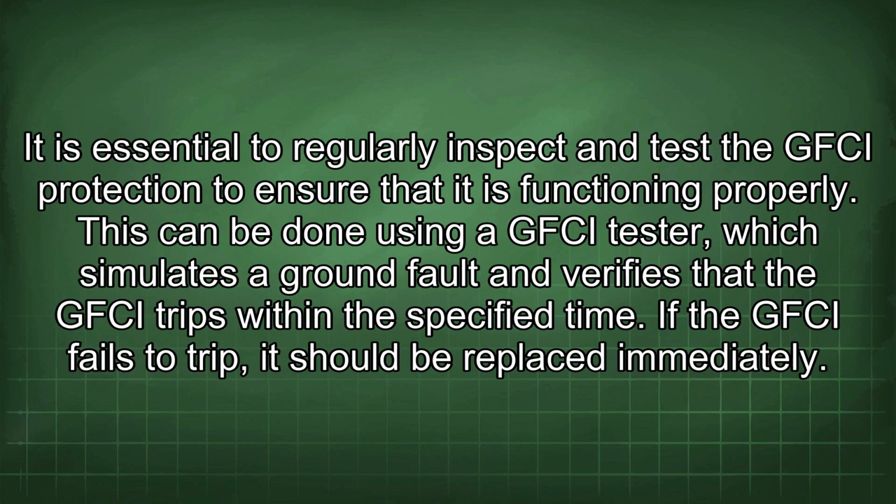It is essential to regularly inspect and test the GFCI protection to ensure that it is functioning properly. This can be done using a GFCI tester, which simulates a ground fault and verifies that the GFCI trips within the specified time. If the GFCI fails to trip, it should be replaced immediately.